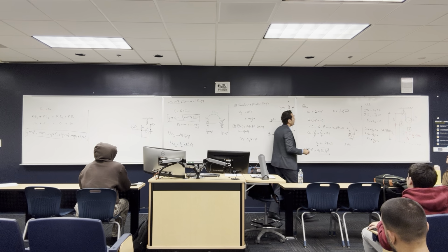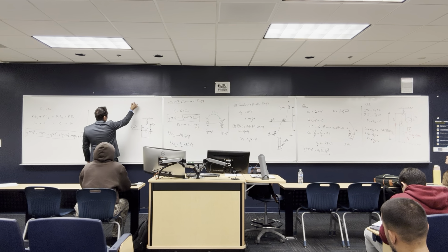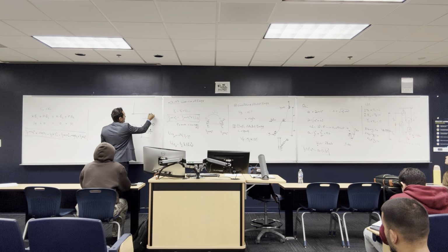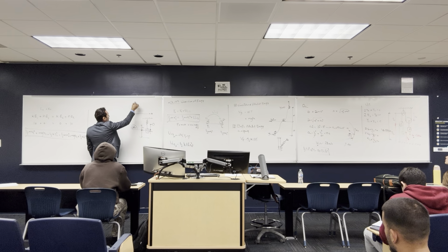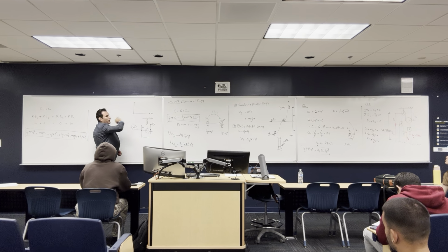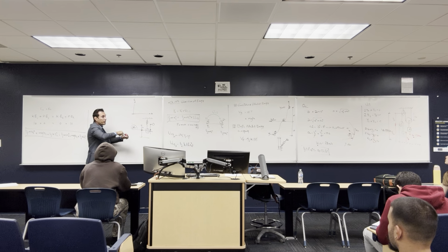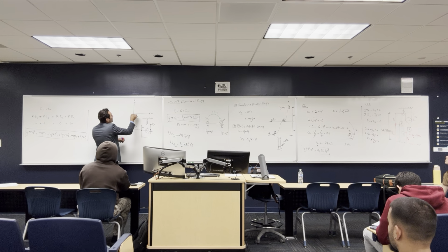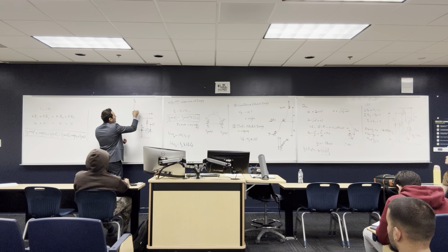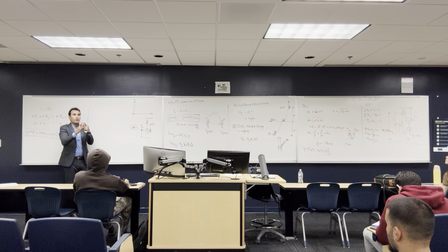I'm not sure if you study materials, but we have something called the stress-strain relationship. If we take a steel sample in the lab, do you guys study this? You measure the yield of the steel and keep pulling. As long as the relationship between the stress and strain, or the Fy and delta, is linear, once you release the load, the sample is going to get back to its original position.